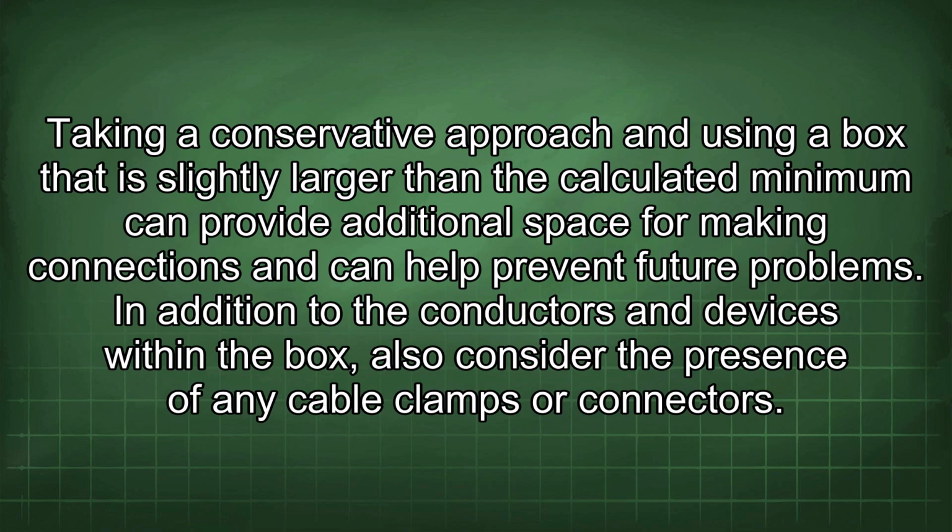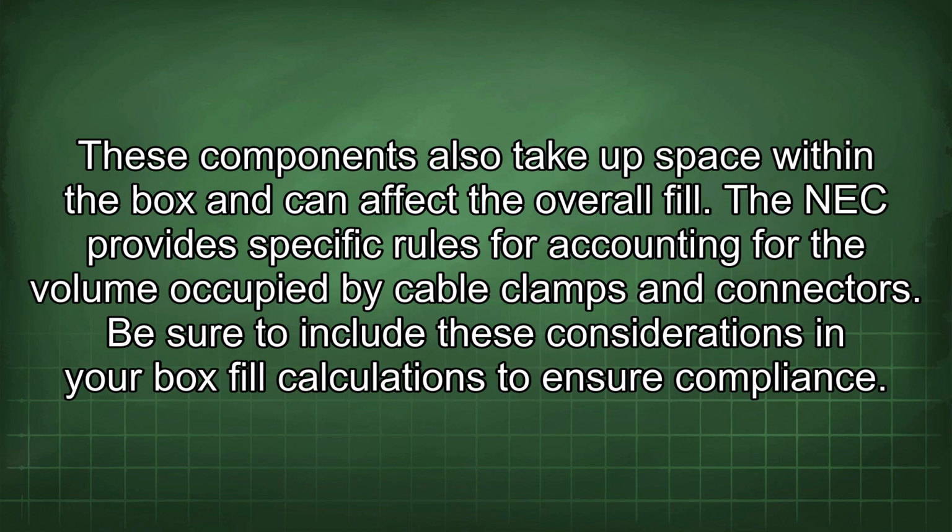In addition to the conductors and devices within the box, also consider the presence of any cable clamps or connectors. These components also take up space within the box and can affect the overall fill. The NEC provides specific rules for accounting for the volume occupied by cable clamps and connectors. Be sure to include these considerations in your box fill calculations to ensure compliance.